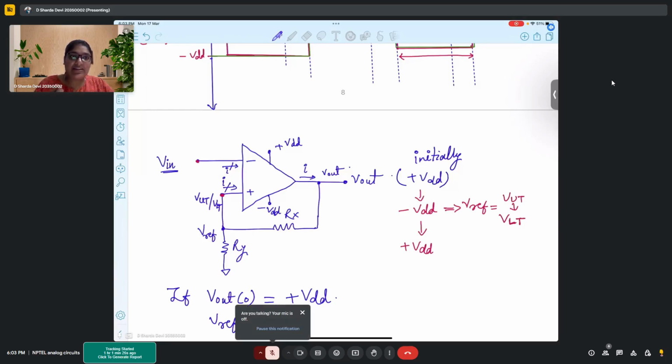So when that frequency matches the noise frequency, there are multiple frequencies in a noise. One particular frequency of noise will match with that of resonance frequency of your oscillator circuit. So that particular frequency starts to resonate and it amplifies, and at the end you get that particular frequency in your output. That is the idea.